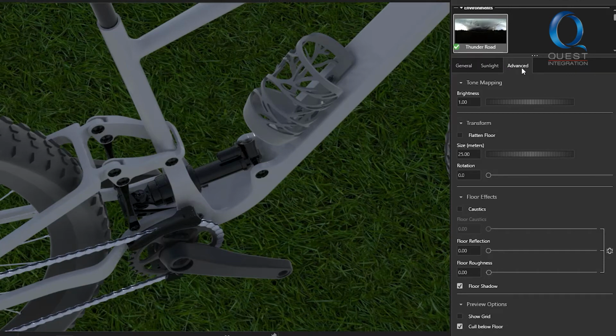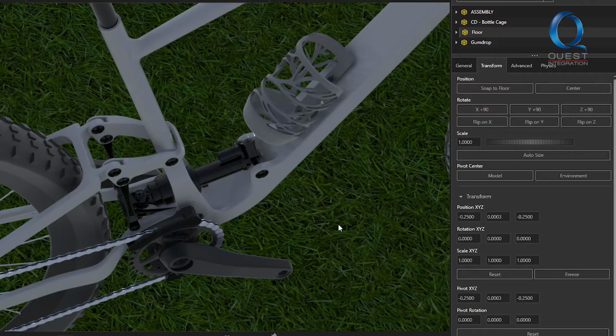It is worth mentioning, the grass that we see in the background here is not part of a backplate. It's an actual part I created in SOLIDWORKS and applied an appearance to. The light from sun studies doesn't affect backplates, so if you want the background to fade in and out with the model, it'll need to be created as a physical item.